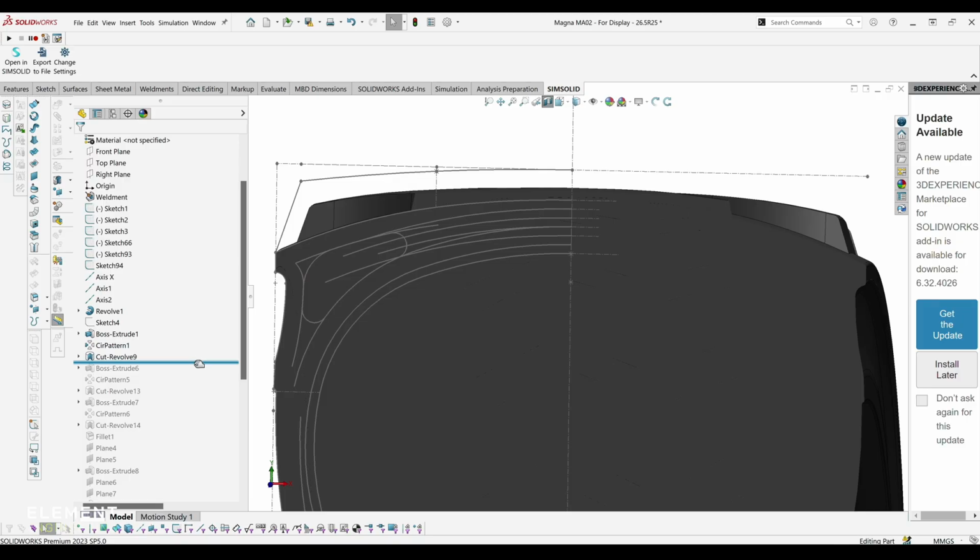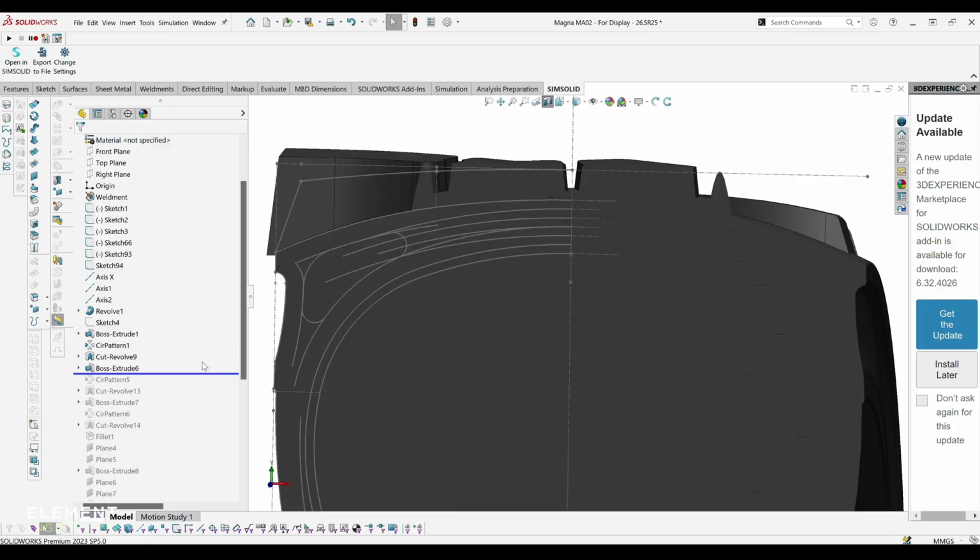Yeah, so I think the way we do it now is different. This is the old way, I'm pretty sure. This is a more simplified way of doing things. It looks good enough, and it depends on the lug pattern as well. If the lug pattern is quite chunky, then this way of doing it is not really the way we want to be doing it, because when you do an extrude, you're going straight down, but that's wrapping around the radial profile. Most of the lugs will be radial from the center out.